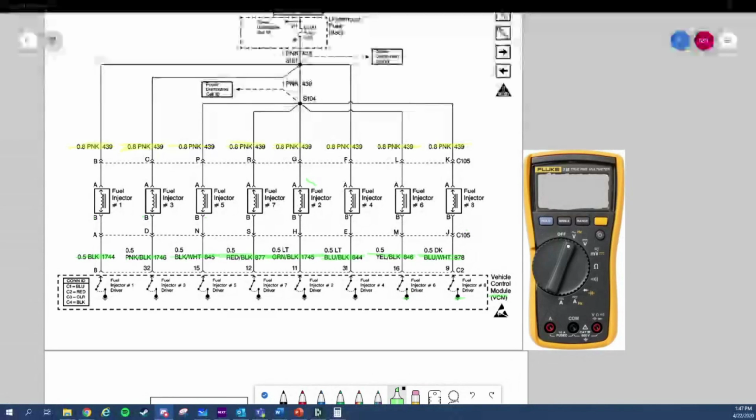Ever since I put it on or been working on it, it hasn't turned off, right? Good. I think, remember when we were checking out that switch, the reason your car was turning off or not turning on at times was part of your ignition unit. Because the resistor was pretty much bypassed.